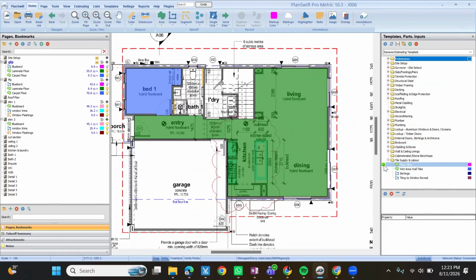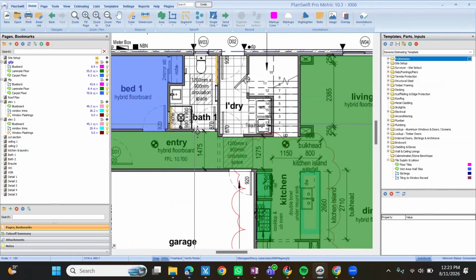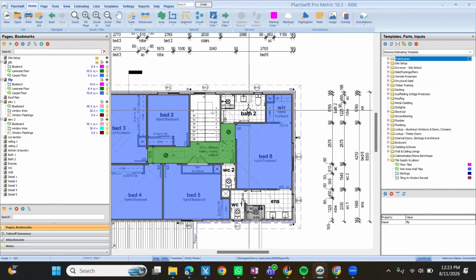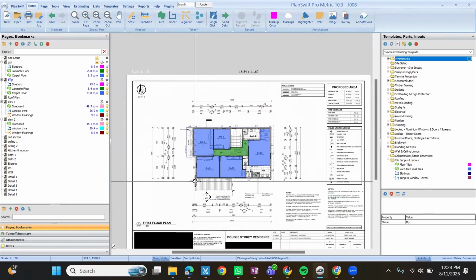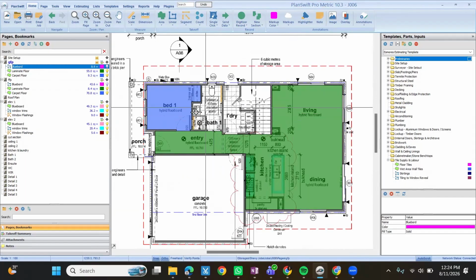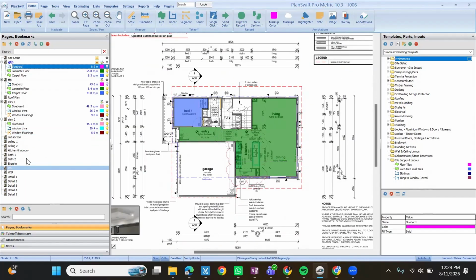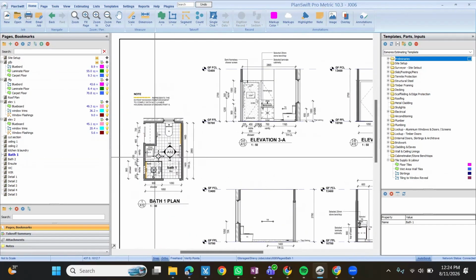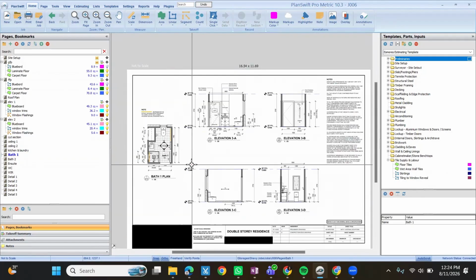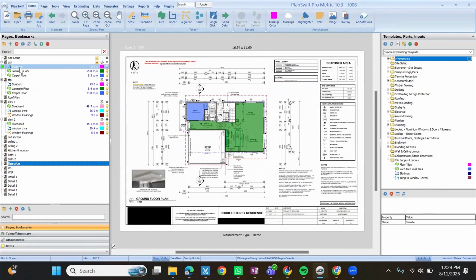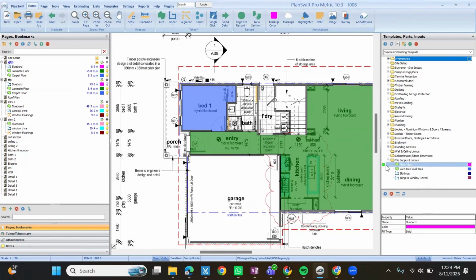So first of all, when talking about tiles, we need to talk about floor tiles. Basically, in this plan, as you can see here, there are tiles here, also on the second floor, here, and also here. Most estimators can do the takeoffs for floor tiles in this plan. Also, if you are given a complete set of plans, you can use those detailed plans for knowing the area of the floor tile. But again, we don't have to use all of this. We can just use the floor layout plan.